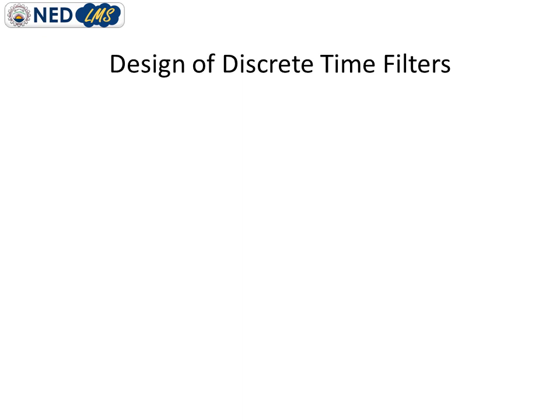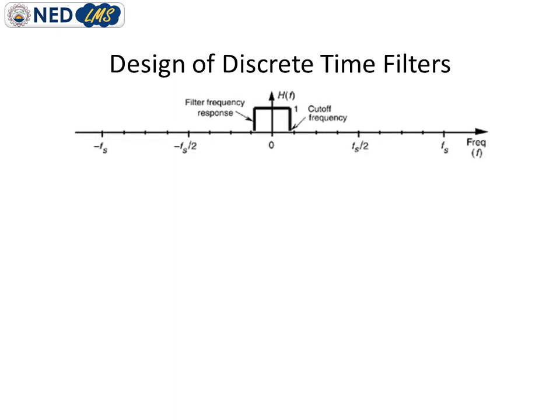So we have to start our procedure by first deciding what frequency response we want for our filter. For example, just for understanding, I have selected a low pass filter design here. You can see the plot.